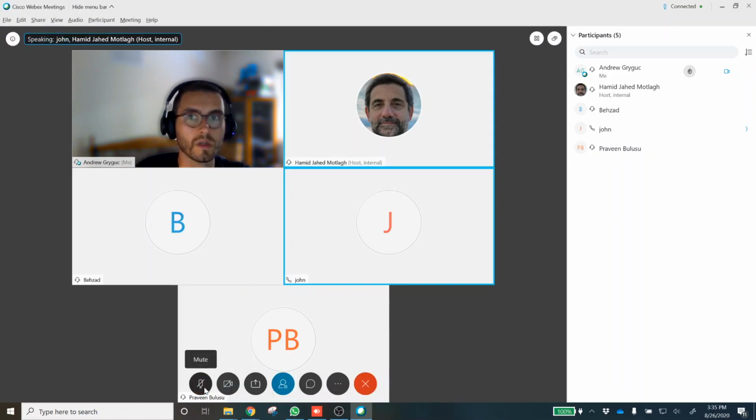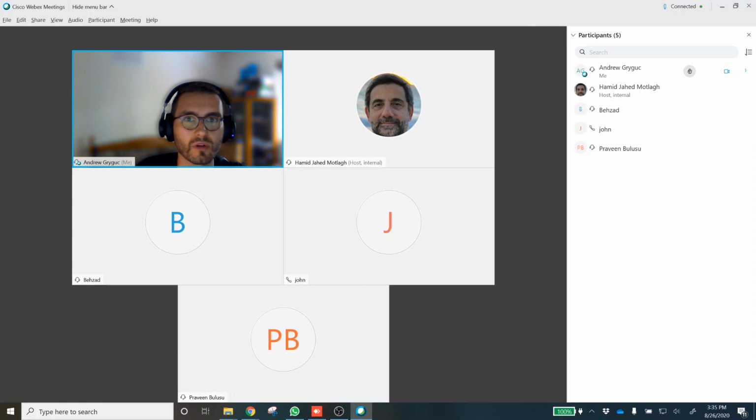Okay. Just a quick question. You mentioned there are M14 to M16 bolts. Is it for suspension, or is it for something like the cylinder head of the engine? Are they torque to yield fasteners? It is suspension. They are suspension bolts. They're not torque to yield. Sometimes Honda doesn't do that.